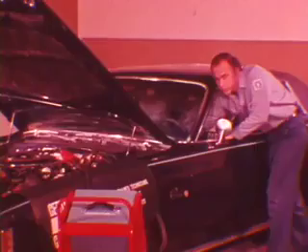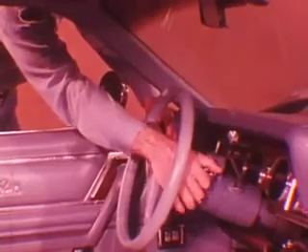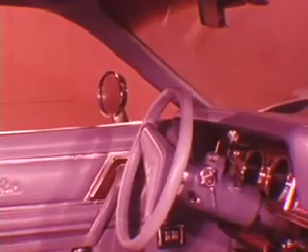When code 4 appears, you are instructed to crank the engine until a code change is seen, but for no longer than 5 seconds. When code 5 appears, release the ignition switch from the start position and allow it to return to the run position.